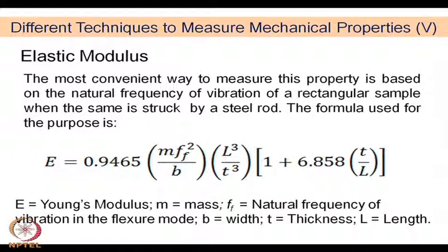So, it measures the vibration over a period of time and then finds out the natural frequency of vibration and finally provides you this Young's modulus. So, it is mathematically a little complex to otherwise measure, but there is equipment available and the software is also available which can directly provide you this number, the Young's modulus.